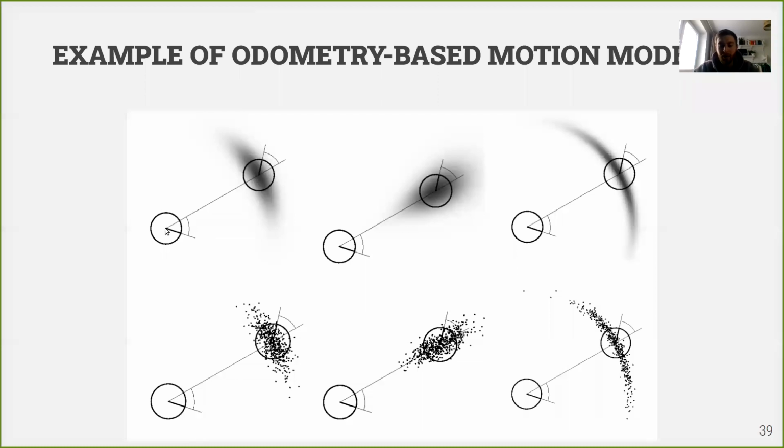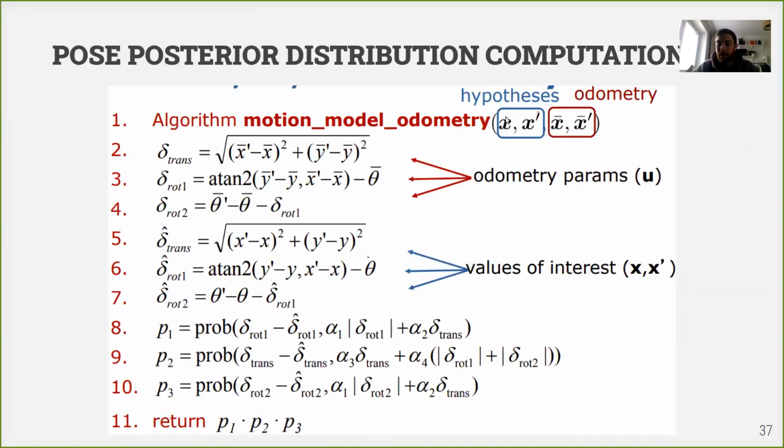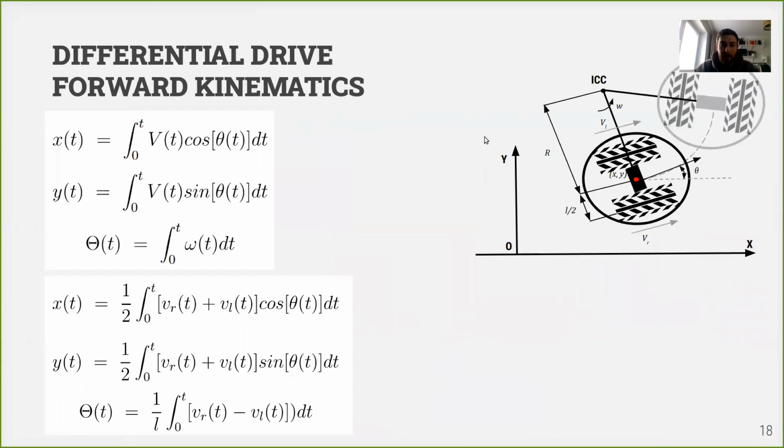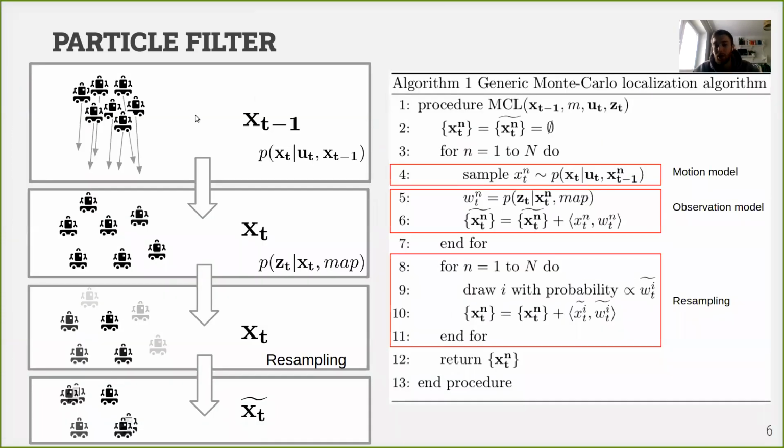So first of all, we know our encoder's readings, right? So we know the estimated pose. But then we're trying to generate a distribution around that because we know that we are not precisely in this place. And we can just check any position around this place, and call any combination of X, Y, and theta a hypothesis. Or there is another approach. Last time we discussed the particle filter, right? And this is actually the most popular algorithm working with particles or hypotheses.